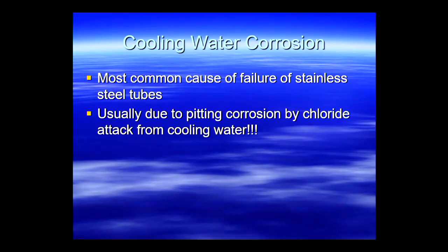Now the problem is this. As you dose more water into this and the cooling tower's evaporating it, of course the salt is getting concentrated. And so there's usually a limit on how much salt you can tolerate in the cooling water system before you end up circulating a mild solution of sea salt through the system, and seawater is highly corrosive. You only have to look at handrails and things down by the seashore to see how badly they're corroded, no matter how much they paint them. So chloride attack in cooling water is a really common problem. So you've got to limit the chloride you have in the cooling water.